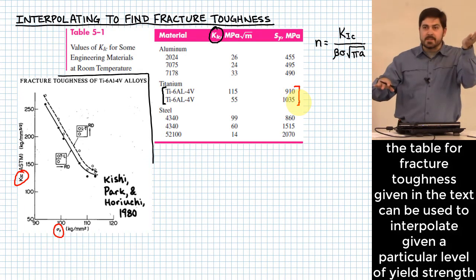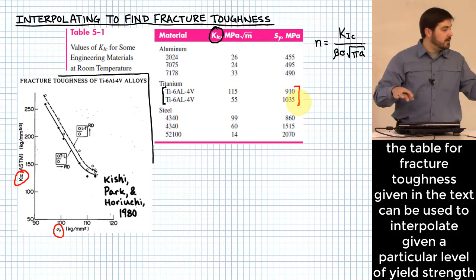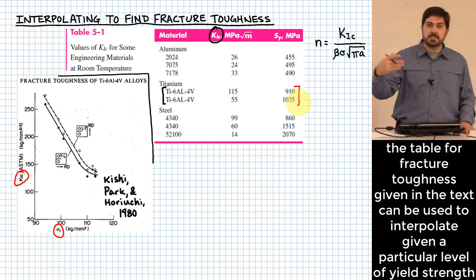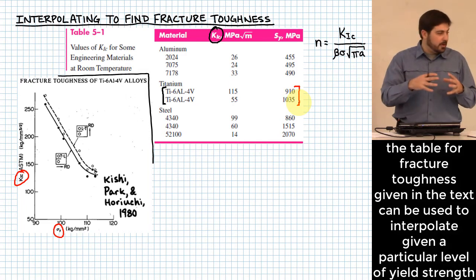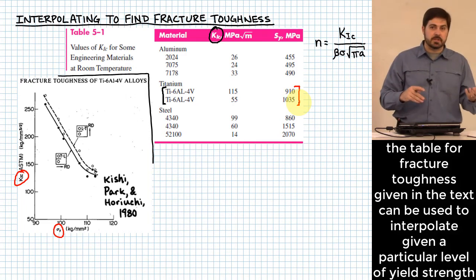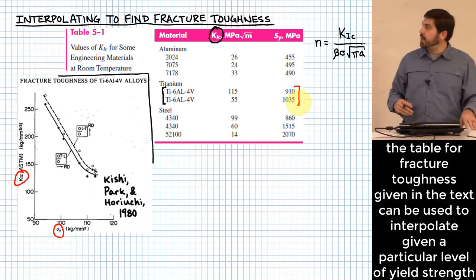Goes down. Why is that conceptually? Okay, cold working does what? Okay, yeah, it lowers the ductility of it, makes it less tough. In other words, you apply a little bit too much more strain to it, it will just start to crack as opposed to yielding some more. Okay, so that's the relationship that we have between those two values. How should we use it?